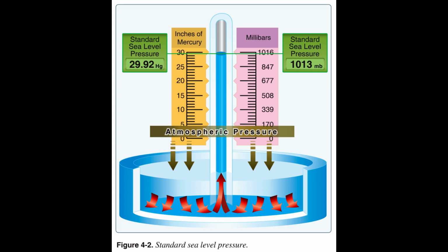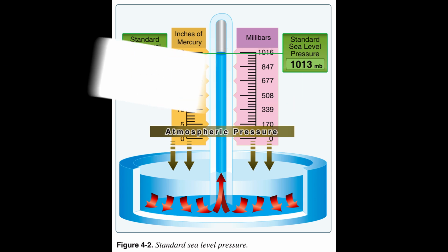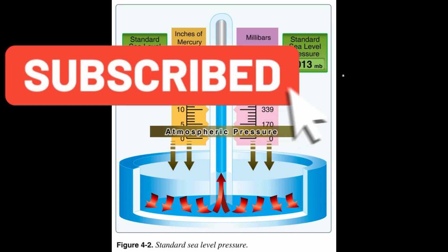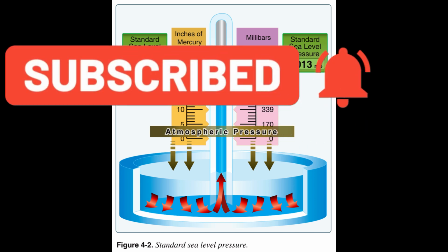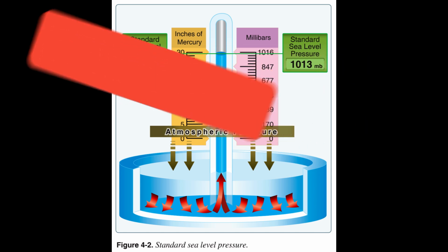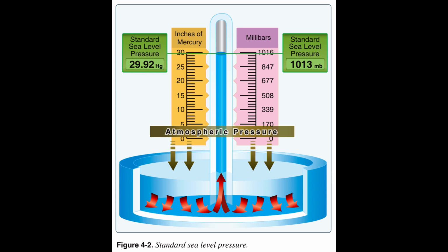Humidity alone is usually not considered an important factor in calculating density altitude and aircraft performance, but it is a contributing factor. As temperature increases, the air can hold greater amounts of water vapor. When comparing two separate air masses, the first warm and moist, both qualities tending to lighten the air, and the second cold and dry, both qualities making it heavier, the first must be less dense than the second. Pressure, temperature, and humidity have a great influence on aircraft performance because of their effect upon density.